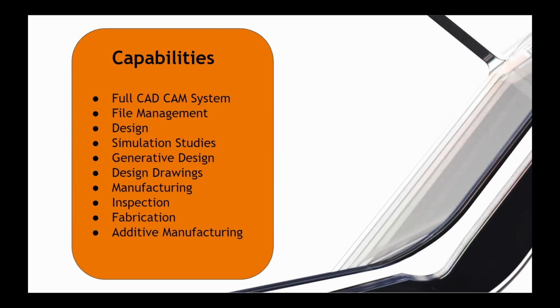You can also use it while it's in the machine, prior to inspecting it outside, as well. You can also use your probe to set up your work offsets, so you make all this a more automated system. That way you don't have to have somebody throw a block in there every single time you're swapping from part to part and have to re-probe anything. You can have all that automated. That's the really nice thing about the inspection part of it.